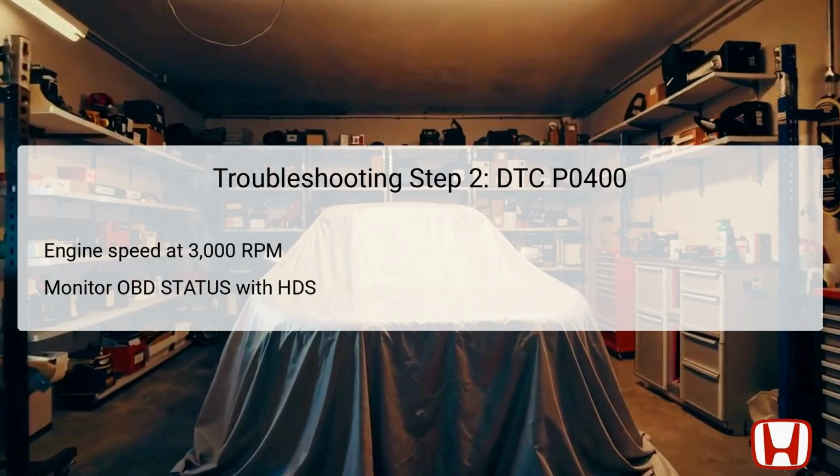conditions. After a 5-minute period of driving under specified conditions, you will monitor the onboard diagnostics (OBD) status for DTC P0400 using the Honda Diagnostic System, HDS. This diagnostic tool will indicate whether the failure can be duplicated in these circumstances, allowing you to understand the EGR system's operational status clearly. In the third troubleshooting step, it is crucial to assess the HDS's indications regarding DTC P0400.